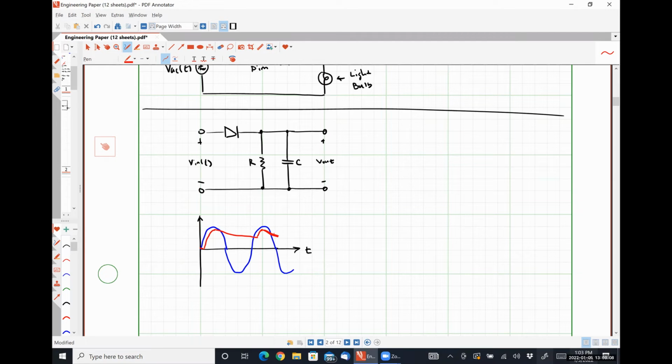So when we turn this circuit on, or when we begin the first positive half cycle of our input, right? We know that our diode shouldn't turn on or start conducting until V in is greater than V D on, which is exactly why we see this little amount of lag, right?